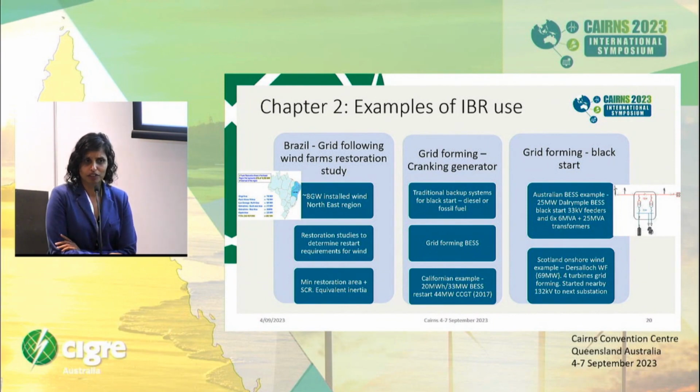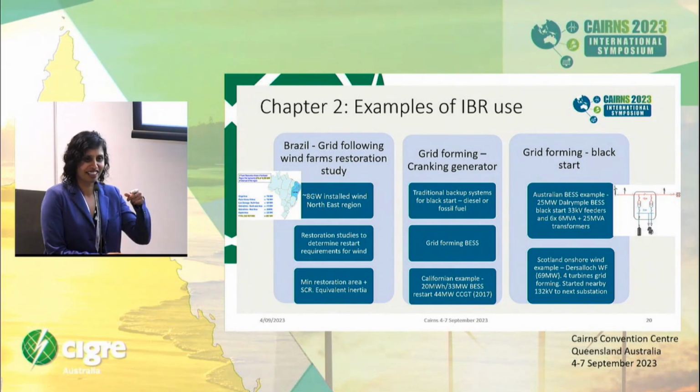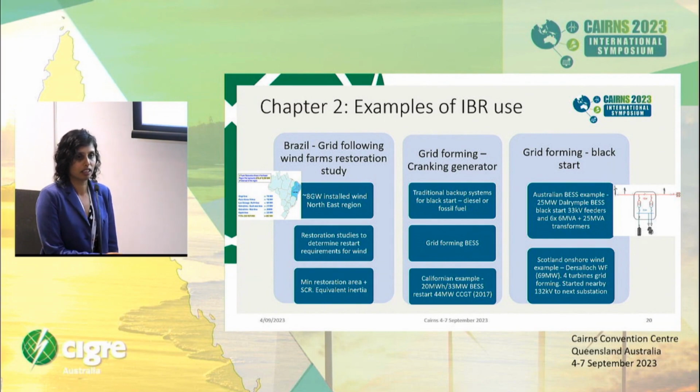Sorry, did you say grid forming or grid following? Yeah, sorry, grid forming batteries. Yeah. So I think in the technical brochure, there were smaller applications of grid forming being used to restart the network. Sorry, what was the second part of your question there? Like where we've reviewed paths to avoid high DER that might push or have really low load. Do you think there's an opportunity if we have grid forming batteries that can go both ways to actually pick up those reverse or power injecting areas?